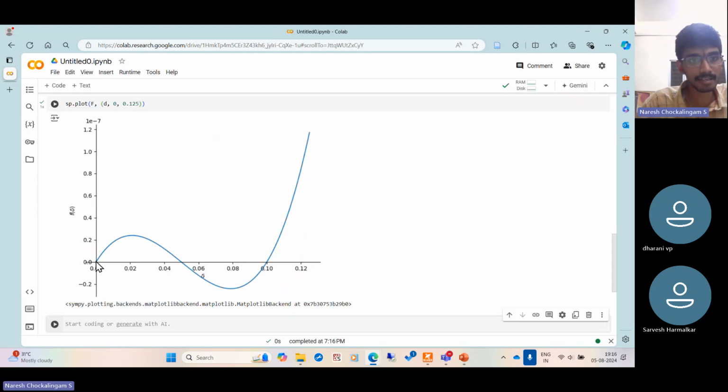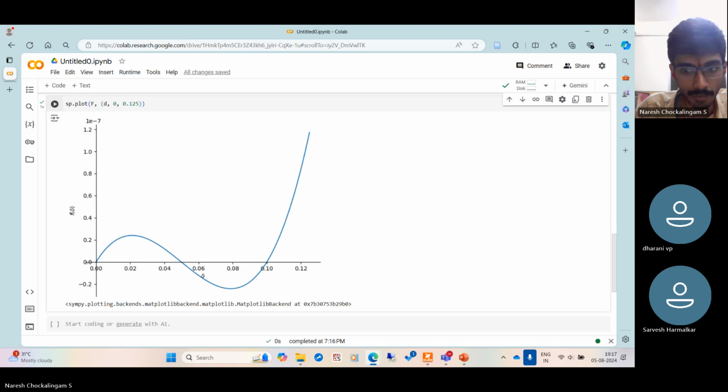Yeah. So what we see is initially as we increase the force, that point B starts moving downwards, right? At some point, we cannot apply any more force without causing an instability. So there is a critical load here. So at this point, the maximum force that can be reached is achieved. Then suddenly, to keep it in equilibrium, you have to reduce the force beyond that point. If you don't reduce the force beyond that point, if you just keep loading it with increasing force, the truss will accelerate and it will go. So I can copy this, put it in the slides.